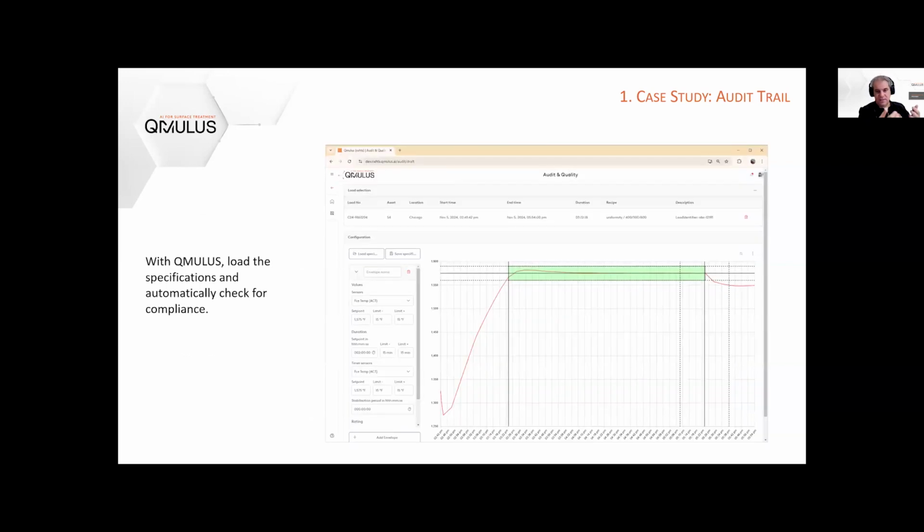All right. So the data is coming in. Your computer knows all of this, and QMULUS knows all of this. Now, if I tell QMULUS, if I'm above 410 or below 390, give me a visual indicator, right? Start when TC1 entered set point minus 3, or when TC1 entered the zone, whatever. I define that start point. I have an endpoint plus or minus tolerance.